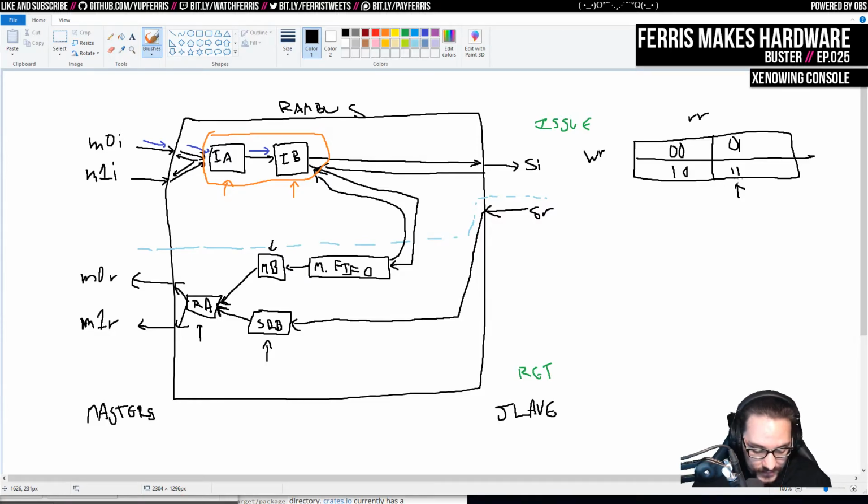So what I decided to do is take the same two signals and replace them. So instead we have enable and then write or read, I should say. And then what this means is not enabled. Let's say we'll put enabled first here. So not enabled and not a read or write, doesn't matter as long as it's not enabled. That's a valid state. Not enabled, and let's say 0 means write, and then 1 means read, which I think is how I have it in my head.